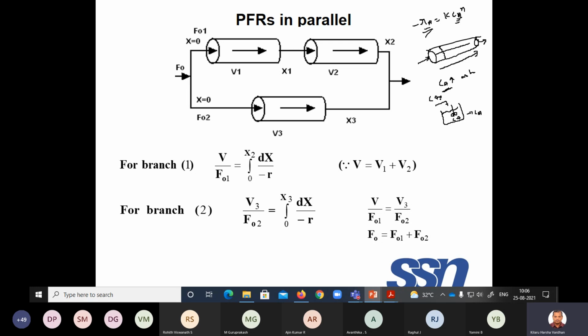As you put the higher concentration feed inside, it is uniformly mixed, so it is suddenly dropping the concentration to Ca, which is the concentration going out. So due to the mixing, the concentration will be as low as possible. Ca is low, rA is low, therefore conversion also will be low.